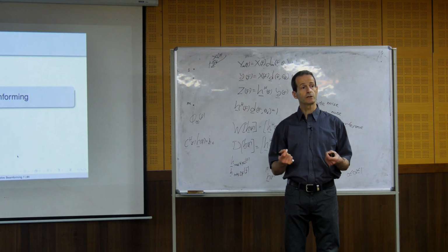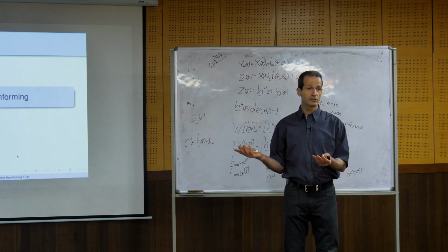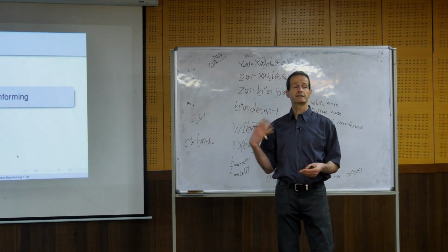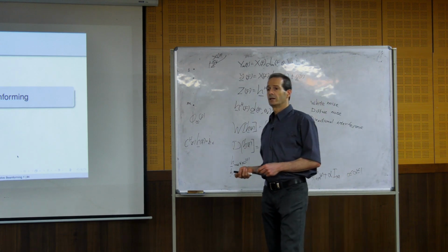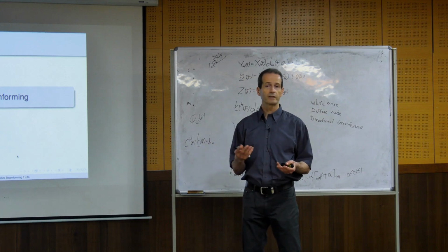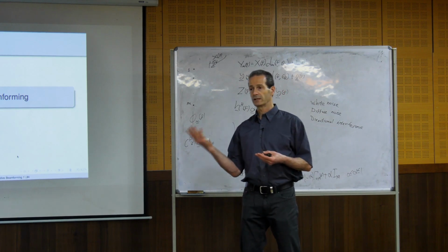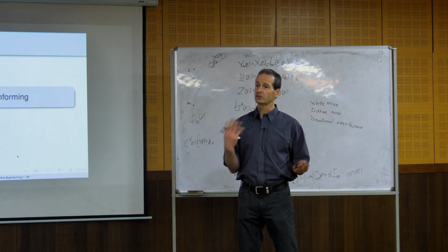Why didn't we work with the beam pattern for multi-channel signal enhancement? Because with multi-channel signal enhancement, we try to estimate the signal. So we can talk about mean squared error, MVDR, and so on, control of the trade-off between distortion and noise reduction, and LCMV with additional constraints.